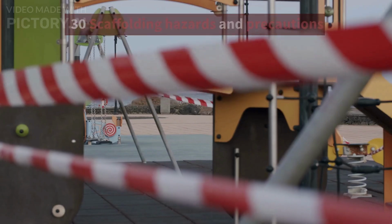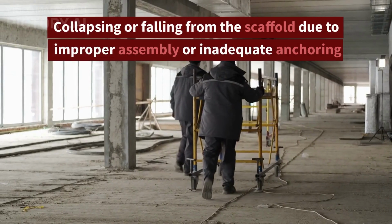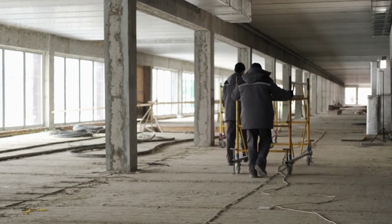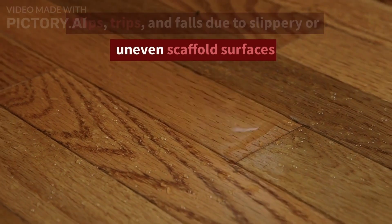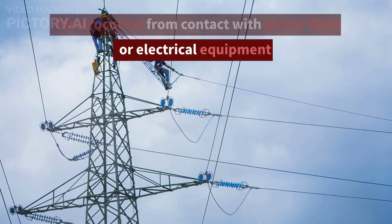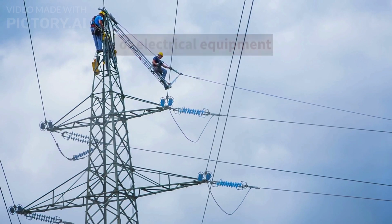30 Scaffolding hazards and precautions. Collapsing or falling from the scaffold due to improper assembly or inadequate anchoring. Slips, trips, and falls due to slippery or uneven scaffold surfaces. Electrocution from contact with power lines or electrical equipment.